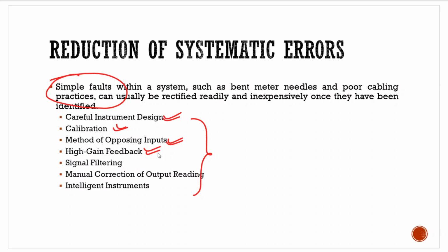That means use proper values of gains etc., so that the error in the system measurement is actually reduced. We can reduce the measurement errors, also the systematic errors, by properly filtering the input variable to the measurement device, by properly filtering out the output value from the measurement device.